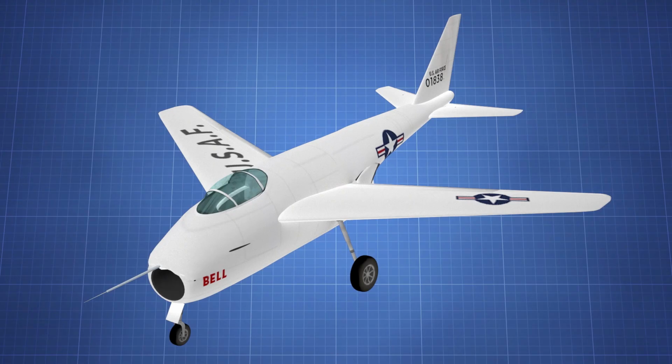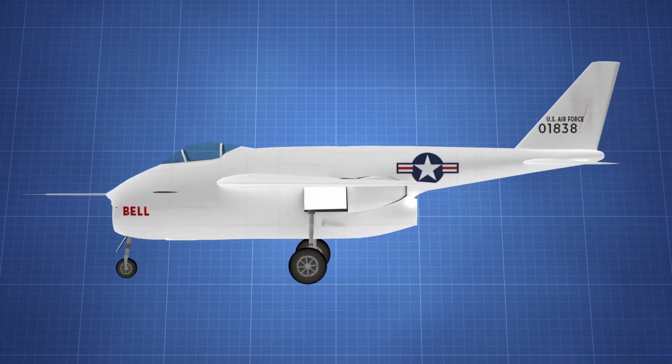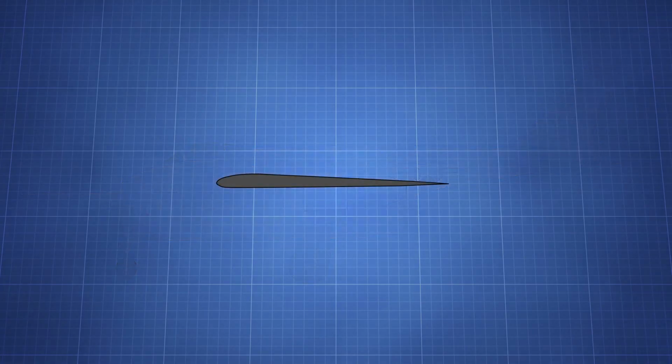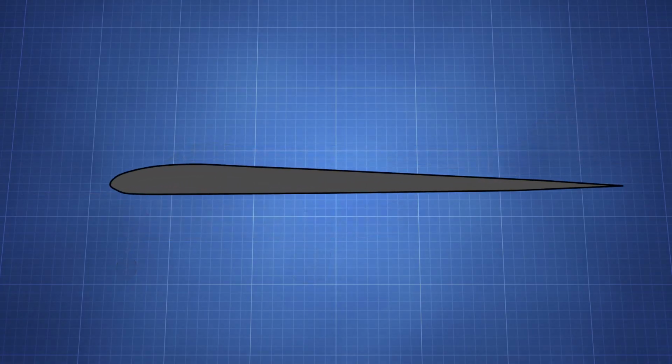Let's discuss it further. But, as you may already know, airplane wings make the air on top accelerate. If a plane flies close to the speed of sound, like at Mach 0.9, the air accelerating over the top could go supersonic, causing shock waves to appear. Of course, as the plane keeps accelerating, the region with supersonic flow gets bigger and the shock wave moves backward. The intensity escalates with each occurrence, significantly increasing aerodynamic resistance and drag. But not only that, it also greatly increases instability because the air might separate after the shock wave. And this causes the distribution of lift force on the wing to change, so the plane starts to move very abruptly.